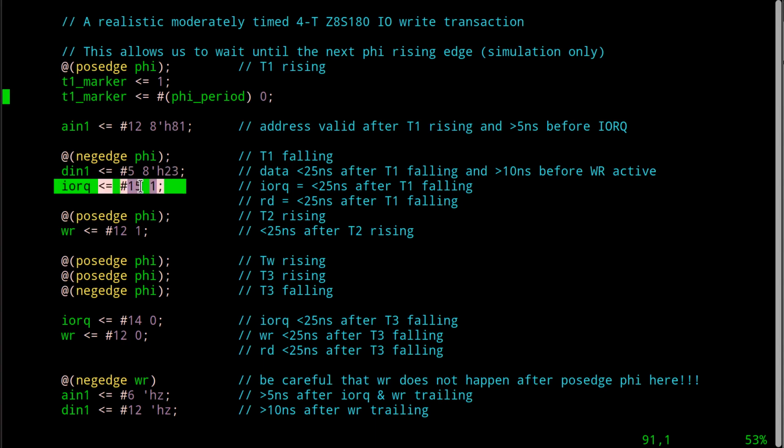15 nanos into the future, do that. And I'm using positive logic in this test bench just to keep my wits, because if half the stuff's positive, half's negative, this is hard enough to do as it is, people. So I usually model everything in positive logic, and I let the compiler change the logic when it actually is implemented, because it will do that to optimize the circuitry inside the FPGA if it turns out to use fewer LUTs and gates and things like that. It's smart enough to do that. If not, get another synthesis tool.